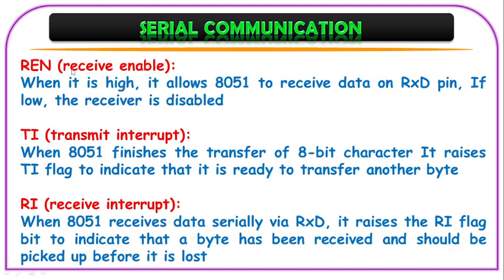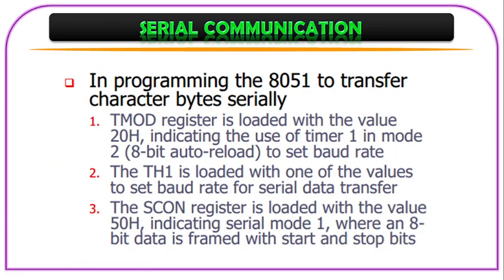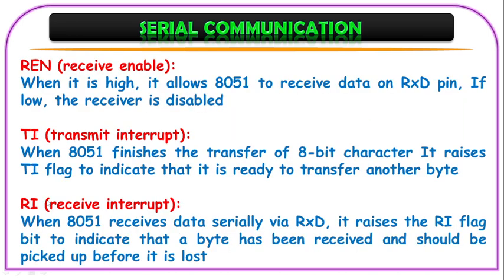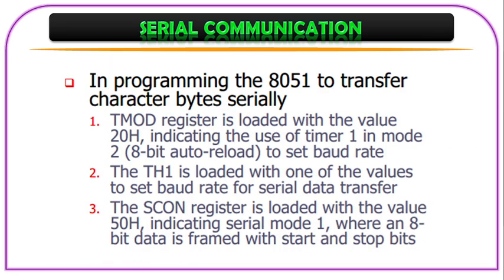And REN is one of the bits of the SCON register, receive enable. It will be high to receive data and also for transmitting data. And then the transmit interrupt flag: when the 8051 finishes one byte of data transfer, it will be high. Similarly, when it receives 1 byte of data, the receive flag will be high. So these two are the flags. We'll be checking the TI flag and RI flag to see whether we have finished the transmission, maybe receiving or transmitting.